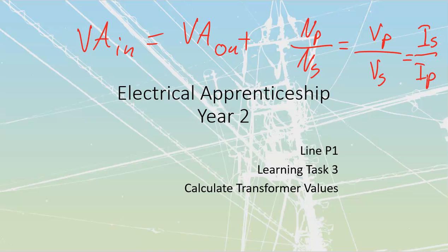We're also going to create a new formula that we haven't dealt with yet, and it's going to be very important later on once we start getting into auto transformers and tapped transformers. It's called volts per turn. Literally, we take these two over here, cross multiply NP down to the bottom, and cross multiply VS up to the top. That gives us this ratio: VS over NS is equal to VP over NP.